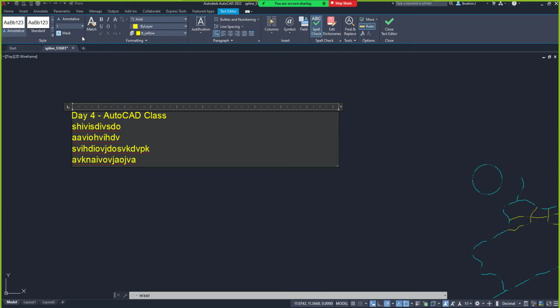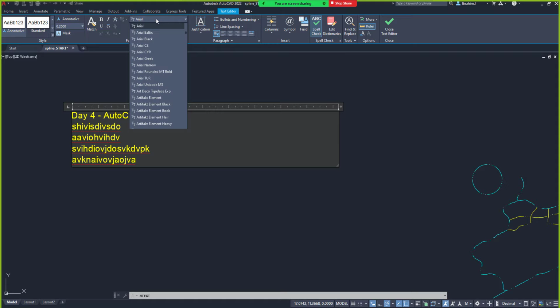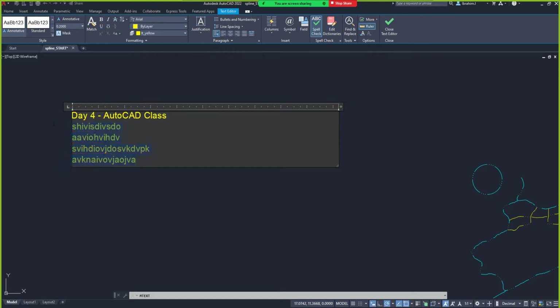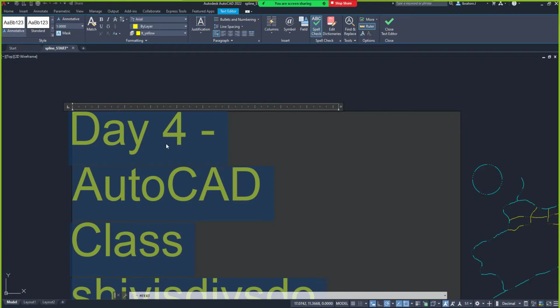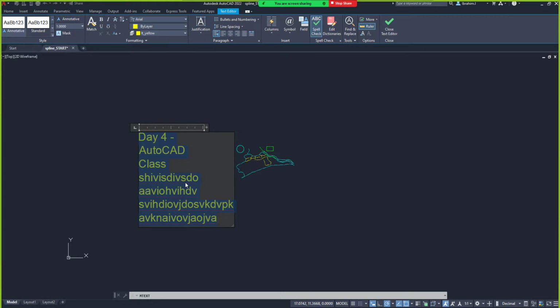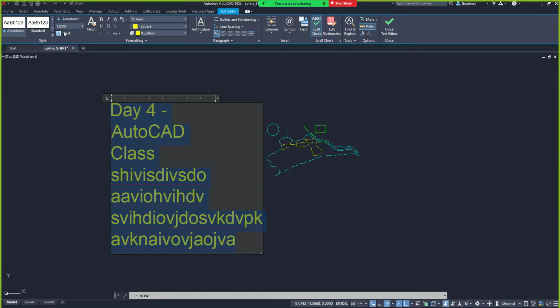Go ahead. After setting that to 1, what do I want to change again? I want to change the text format. I'll select everything and then convert it to what? I'll select all the text first and then I type 1. Then I go ahead. 1. Enter. Okay, you can see that my text size has changed using our text height there.